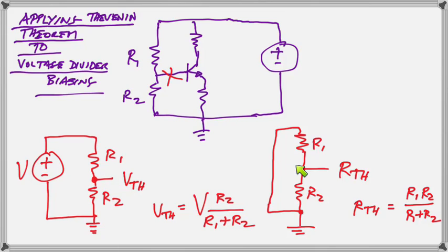And over here now we see that when we remove the voltage source entirely, it's replaced by a piece of straight wire. This is because the internal resistance of voltage sources is extremely small. So if we kill the voltage source, to zero, then there will be no voltage there, but it will behave exactly as a piece of wire. This concept of dead resistance applies throughout electronics actually. The dead resistance here when we kill the voltage source is just the parallel combination of R1 and R2, which makes our RTH.